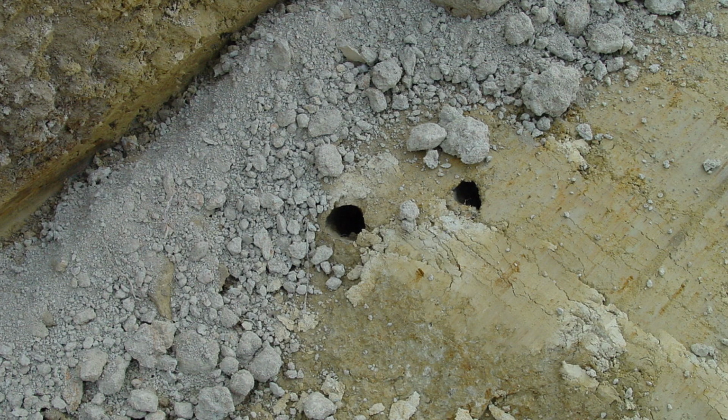This core trench is not being dug deep enough. It must be dug to the bottom of the crayfish burrows that are visible in the trench, or the crayfish that are hidden in the bottom of the hole can dig new holes up to the surface and drain the wetland. We found that crayfish will not dig their burrows in the clay that is compacted in the core trench to form a groundwater dam.